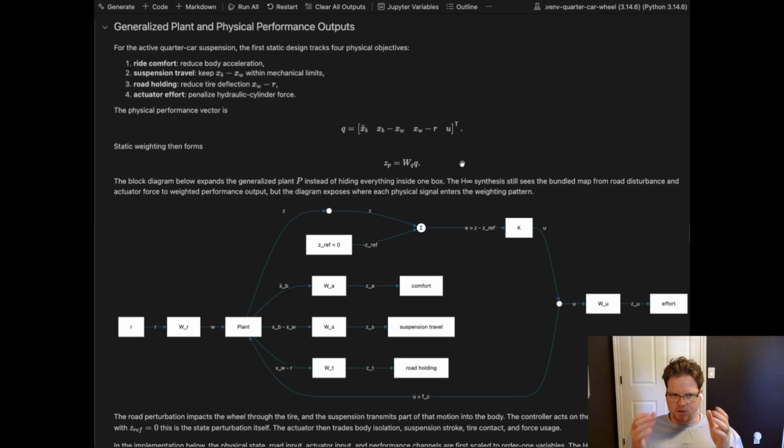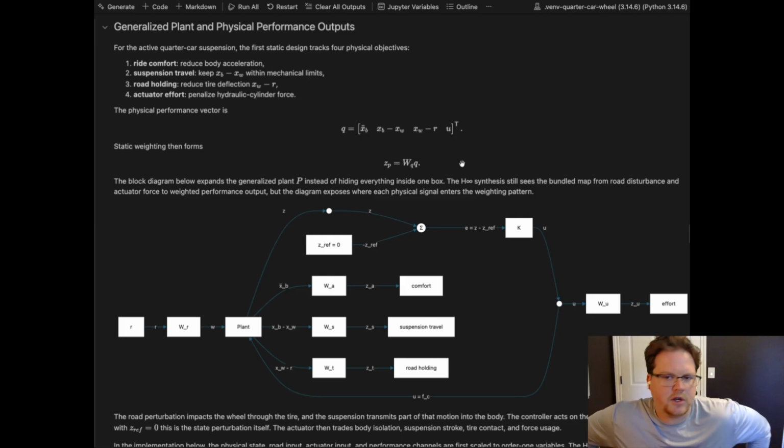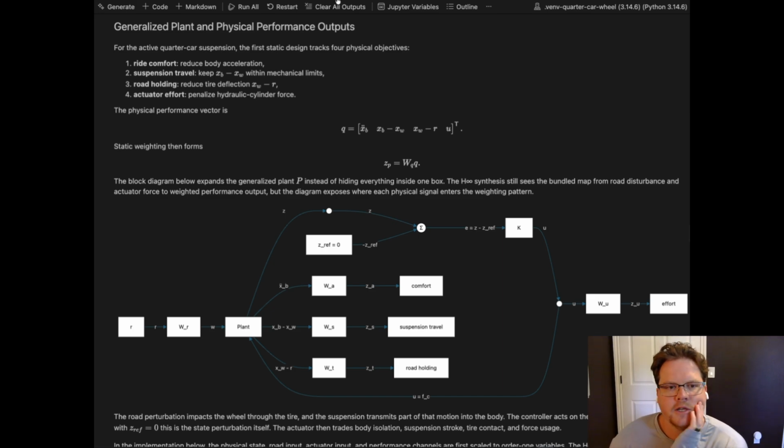But essentially, you could model the U actuation input with a reference governor or a control barrier function or something like that. Something on the input or output that basically governs or makes sure that the U isn't going crazy. But you could also do the clipping too, which I was showing in the cart pole example as well.